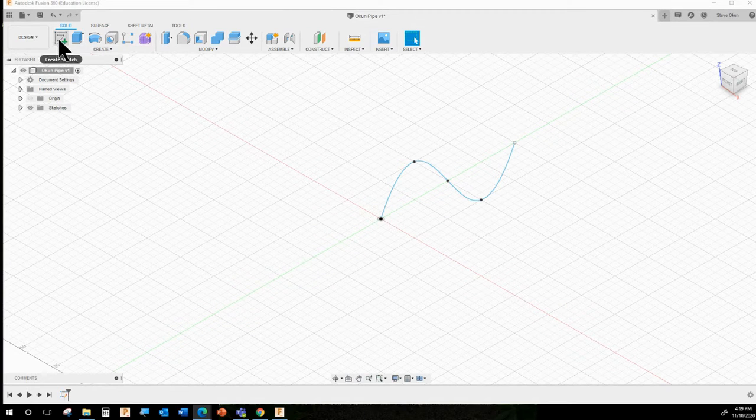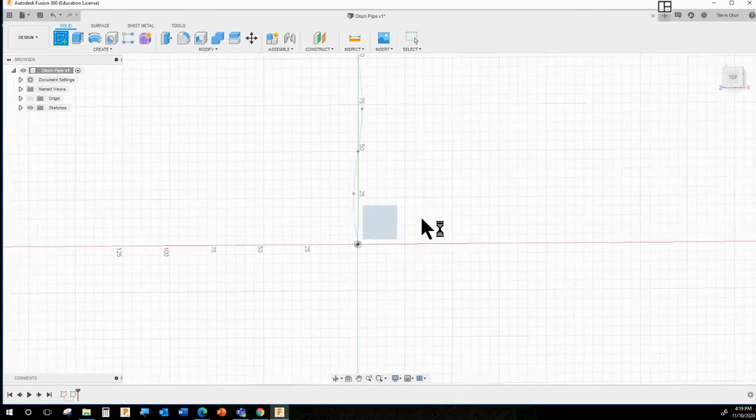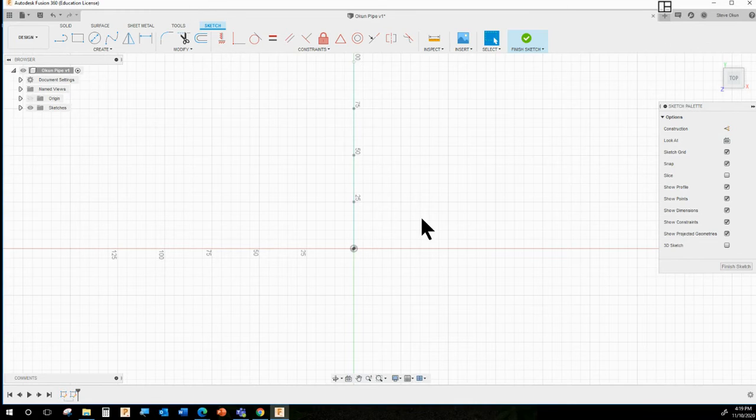In order to do this, we are going to create a sketch, and again, we're going to create this on the ground plane, so it's perpendicular to the pipe and forms a profile. Profiles are an incredibly important part of 3D design, whether you're revolving the profiles or extruding the profiles. Think about the baseboards or the trim in your house, right? There's a profile there that's been extruded, or in this case, we're actually taking a profile and sweeping it. And eventually we'll learn how to loft too.